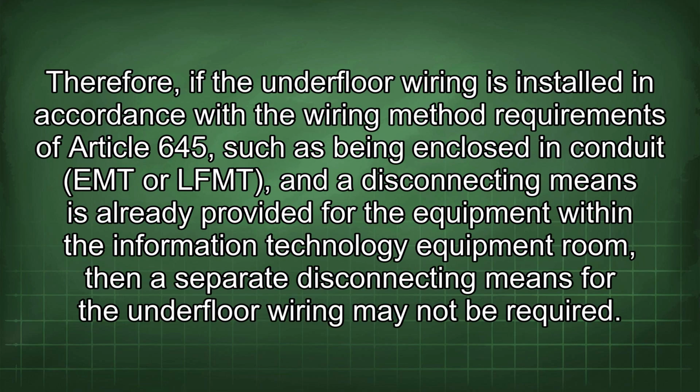Therefore, if the underfloor wiring is installed in accordance with the wiring method requirements of Article 645, such as being enclosed in conduit, EMT or LFMT, and a disconnecting means is already provided for the equipment within the information technology equipment room, then a separate disconnecting means for the underfloor wiring may not be required.